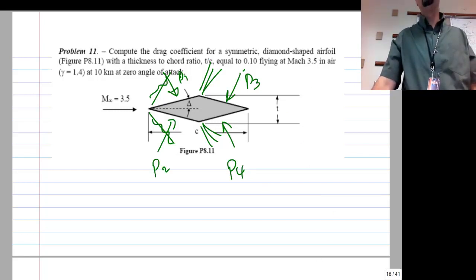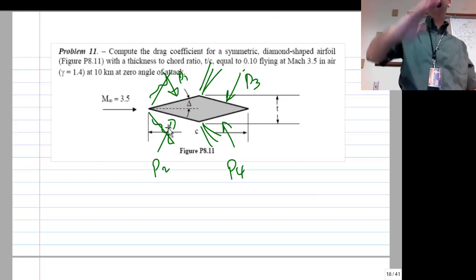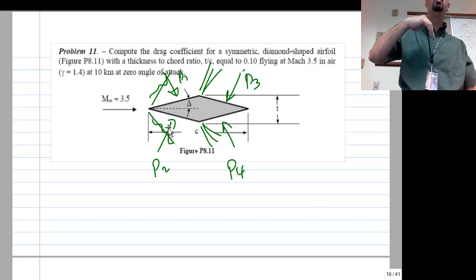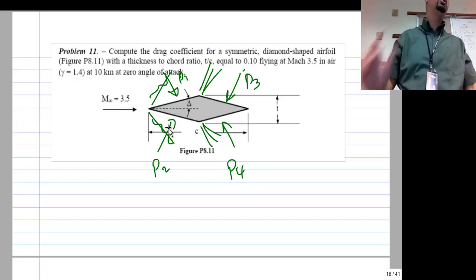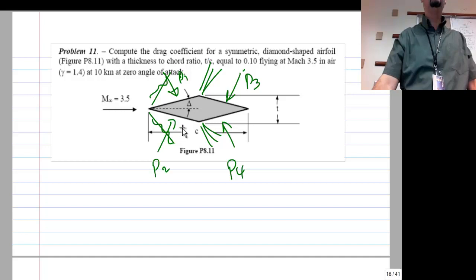So for symmetry, basically, you will not have any lift, but you have drag. So obviously something like this will have to generate lift. What you need to do? You need to have an angle of attack so that you would kill that symmetry, basically. Right?